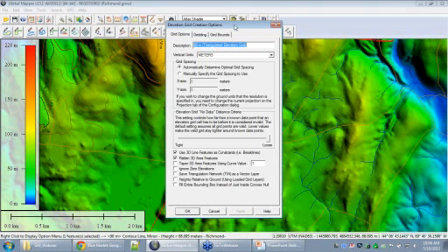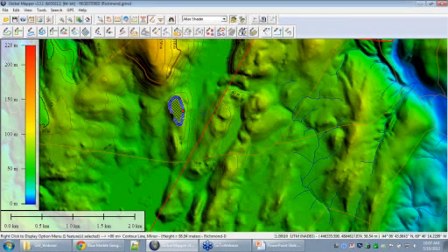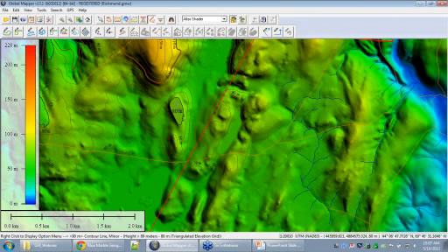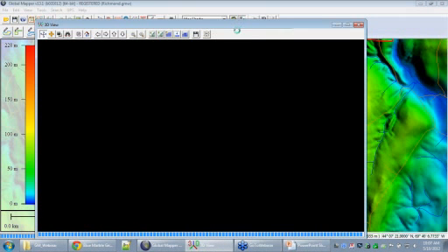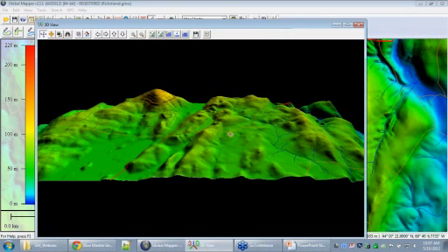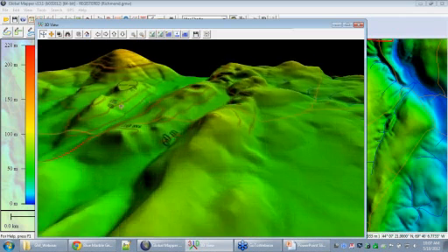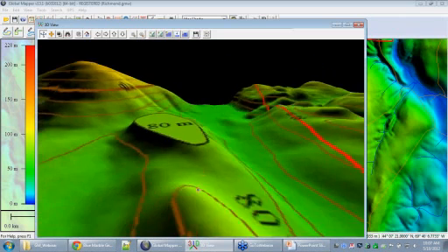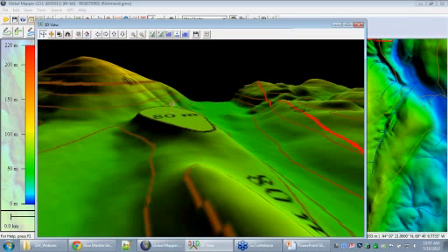So if we select that, what that's going to do for us is basically create a little subgrid in my elevation model. If I flatten that out, I'll just deselect that. You'll see it actually flattens out. The shading on that turns similar throughout the area corresponding to the elevation in the elevation shader. And if I pop that into the 3D viewer, once that renders, you'll see the top of my hill has now been sort of cut off there, and we're flattening that out into the plateau.